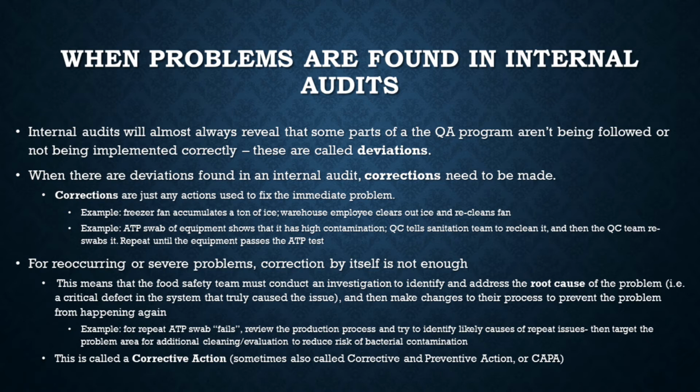Now, let's say you already finished packaging that soup after it's been cooked, and you assumed it was 250 F for 4 hours, but the QA person checks the records for the temperature recorder and notices that it's actually been under 250 F for most of the cooking time, let's say 3 of those hours. Well, now you have to dump the product, write the report for disposing of it, or reprocessing it. Maybe you need to recook it.